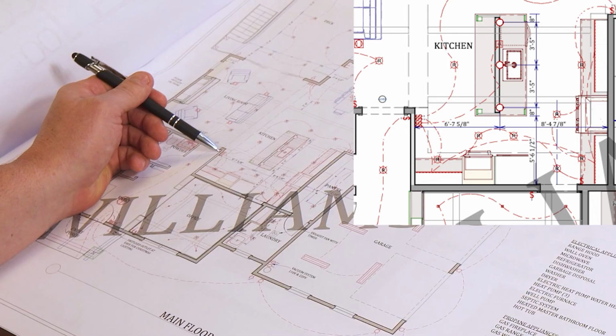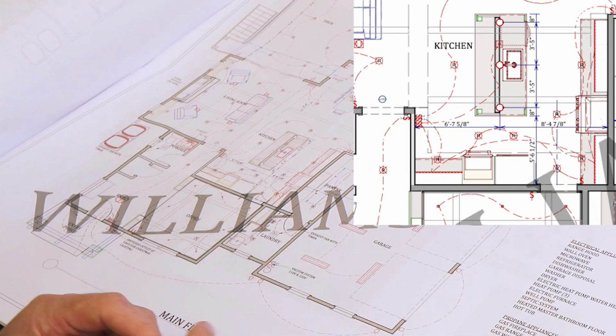As we're following the switch legs, it's really important to see where lights are switched. In this instance, we have a switch with a number 4. This 4-way means there's 3 total switches on these lights, and you really want to look at where those switches are. When we're switching an electrical plan, we're thinking about primary point of entrance into the room, primary point of exit. If you're going to bed at night, do you have to walk across the room to turn off a light, to turn off the main lights, and then go through that room to then go to your bedroom? So we're looking at ingress, egress of the rooms.